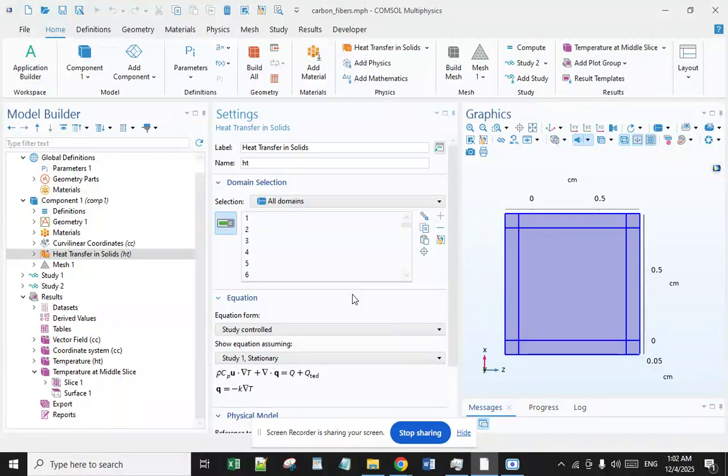The obtained heat transfer coefficient was compared with that of single fibers and packed beds for a wide range of Reynolds numbers. The heat transfer coefficient of a fiber cluster showed a much smaller value than that of a single fiber at very low Reynolds number. This result implies that the heat transfer coefficients of fibrous or porous media at low Reynolds numbers don't approach those of a single particle or fiber.